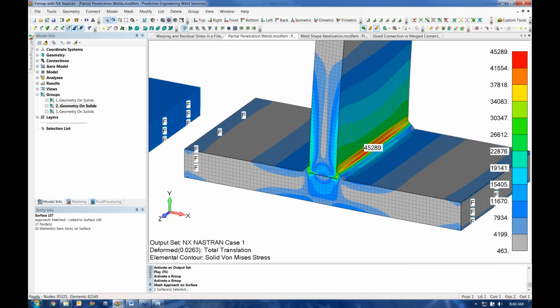So this is kind of the first step here. You have to think about, do I have full penetration welds? Is the stress in my parent material going to be about the same as the stress in the weld? Or am I choking down and forcing all of my load to pass through small areas like this here?